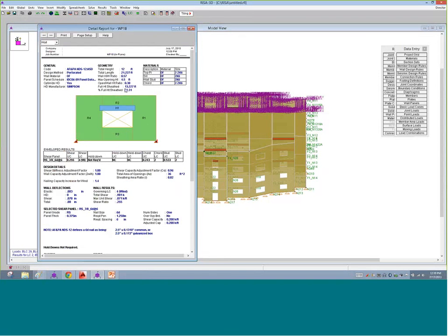And all these calculations, pretty quick hand calc type things, get factored into what is the total unit shear and what is the total shear being applied into this wall, and then we get a ratio of which panel gets selected for this actual wall here. So it's a nice hand calc method. You can see all the factors you need to do that hand calc method are here.